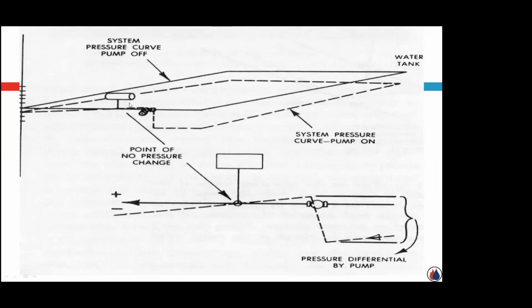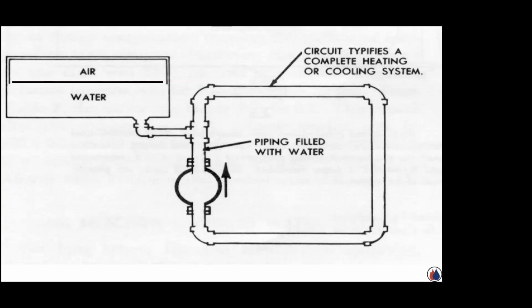These couple of drawings are older, so they're showing an old steel tank. The exact same principles apply to diaphragm and bladder tanks. And real quickly, this is a 2-second dissertation. The reason that whole principle exists has to do with this: water is not compressible. Air is a gas, and a gas is compressible. The only way I can change the volume of air, which would mean changing the pressure of the air, is by changing the volume of water in this hydronic system.